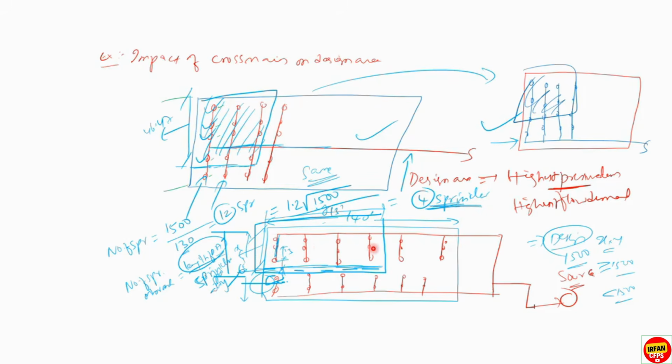So 3 again will go back, again go back, go back. For this sprinkler, in between you draw a line, and this length you already know, 46.47. But if this sprinkler is getting in between, don't consider this one. Just create a line in between these 2 sprinklers and draw in this way. You will get this length and this width. So length into width should be more than 1500 square feet for ordinary hazard or light hazard occupancy.